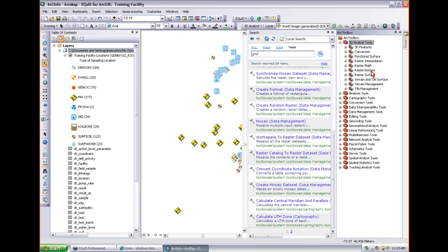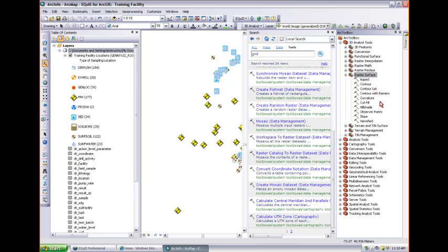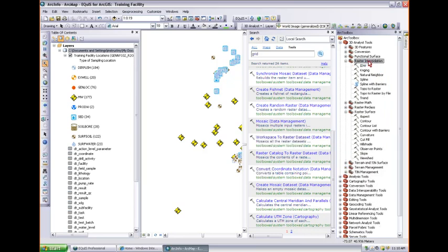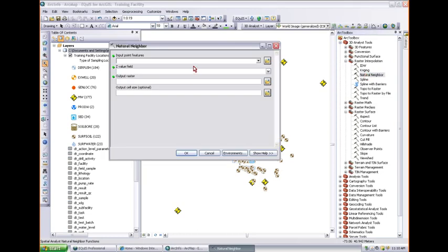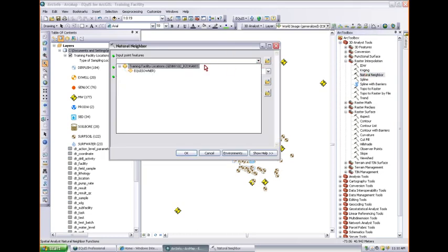We want to create a raster surface, right? A raster interpolation, there we go. So here we have inverse distance weighted. I personally, sometimes I've seen that look okay, but to me it always looks like a bunch of concentric circles, not really representing water level data. But again, what do we have? Kriging, natural neighbors. So this would be a good comparison. Natural neighbors, see how this one, I believe their natural neighbor is a lot less staircasey than their Kriging.